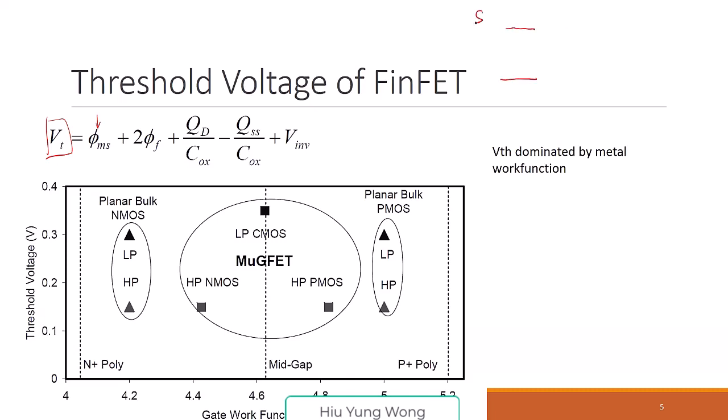This is the silicon, right? And this is the conduction band. This is the valence band, right? From here to the vacuum is about 4.05 eV. Okay. And then, of course, from here to here is about 5.17 eV, right? Because the gap is 1.12 eV.